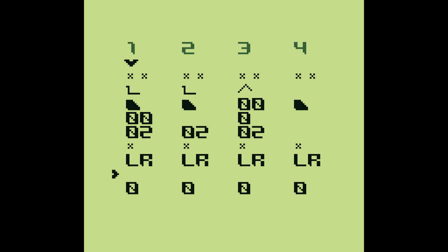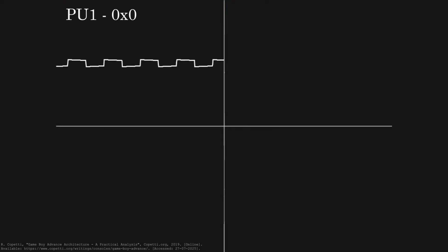From there, these signals can be sent to a connected Game Boy running an instance of MGB that will read them as they come in and convert the associated MIDI signals into instructions for the Game Boy's 4 sound generators. Now, unlike the MIDI 1.0 standard, which is built to work with up to 16 simultaneous sound generators addressed via 16 unique MIDI channels, MGB only uses the MIDI channels 1 through 5 with the hexadecimal address nibbles 0x0 to 0x4 and works as follows. Channel 1, 0x0, is received by the first pulse wave generator PU1.